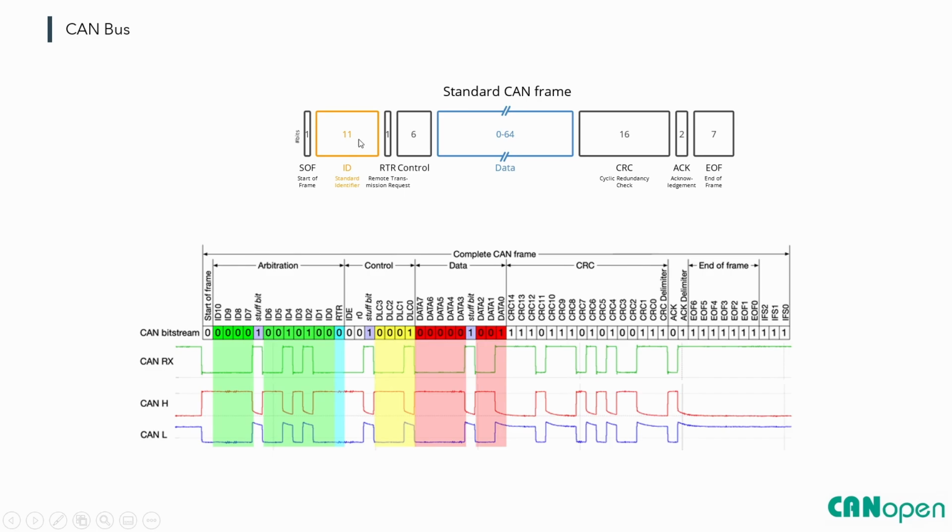It can generate this and transmit it over the CAN bus, and if it receives something like this, it parses that CAN frame and tells us we have new data with a certain ID, or with some data on it, and this is the CRC for that. Usually, as far as I know, most CAN controllers check the CRC themselves. You can see the more detailed CAN frame here.